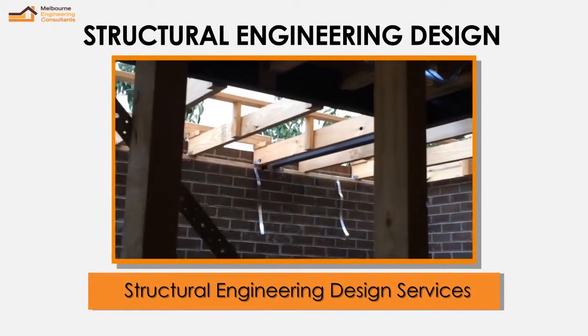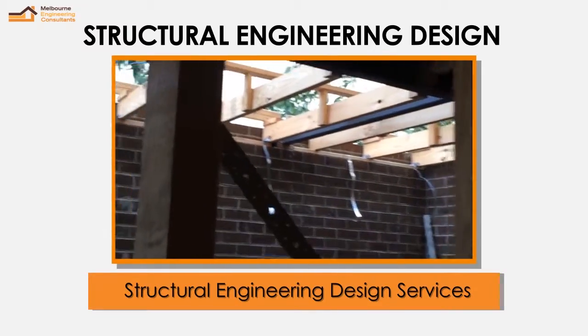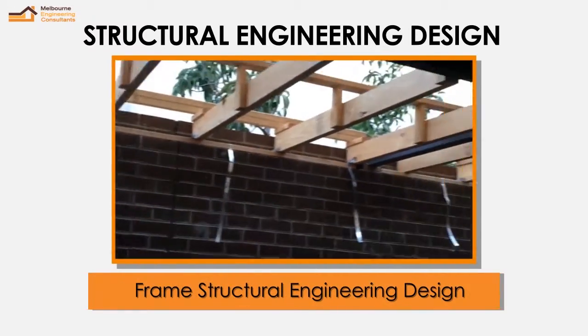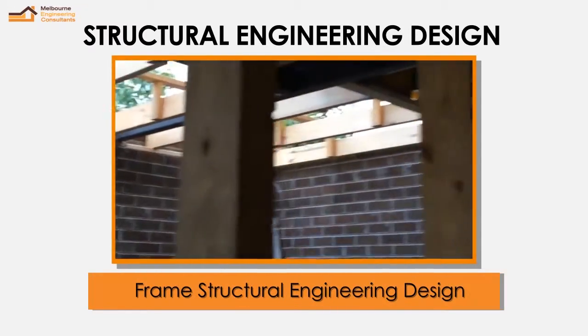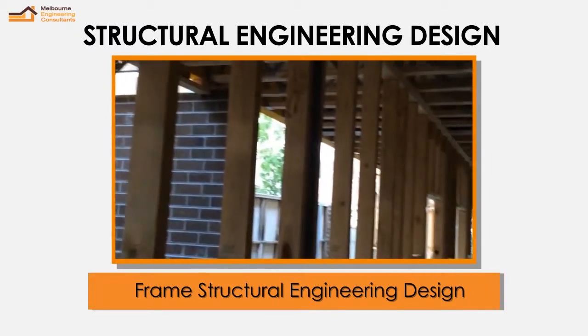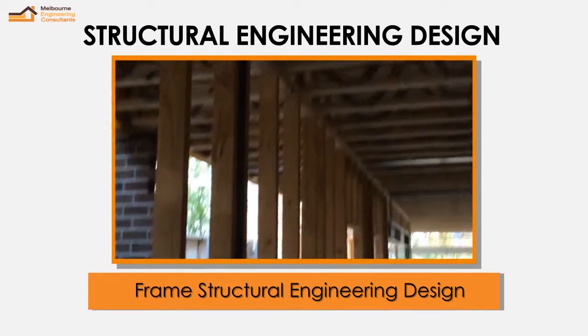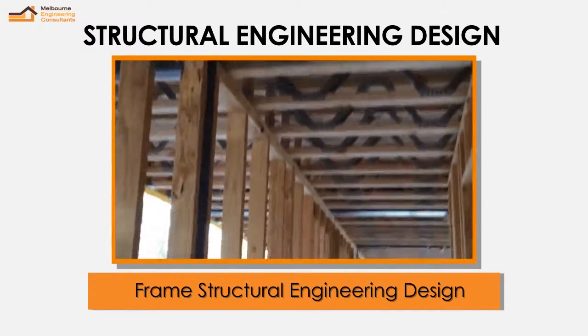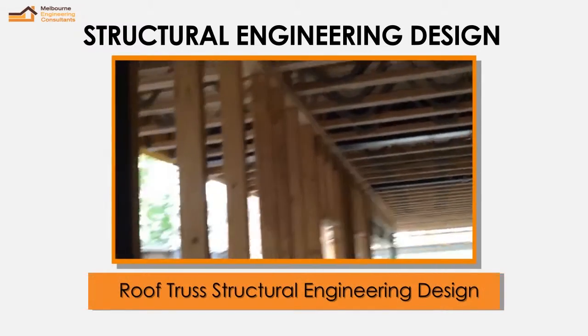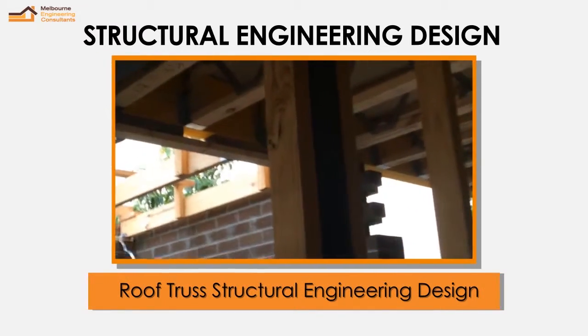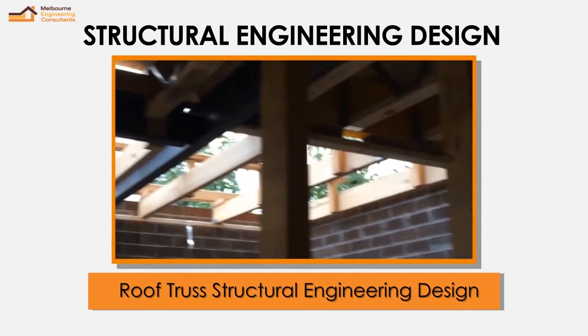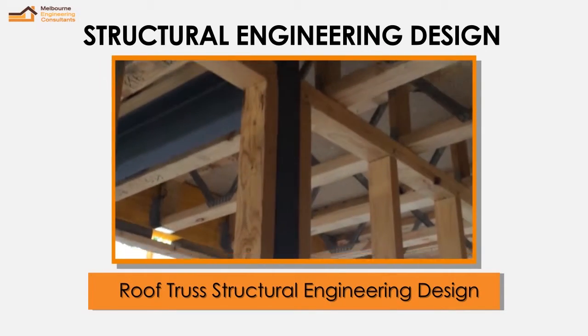Again outside are the roof rafters which are 600 centers which are just for the tin roof, and internals are the posi roof trusses and the floor trusses which are at 450 centers for internal areas. Another one here is a steel beam which is picking my other two major beams, and here's the steel post connection to the beam.